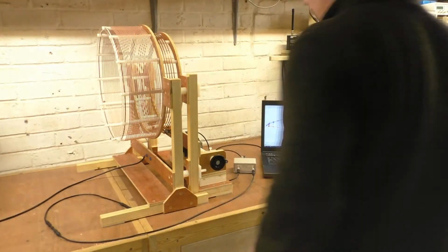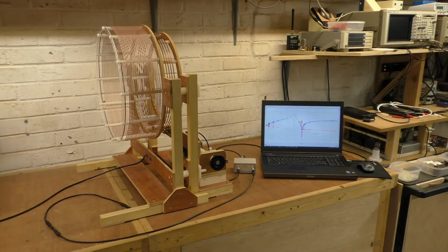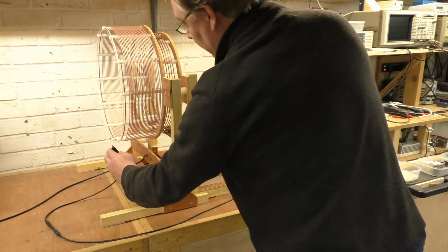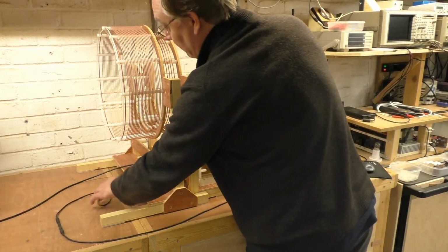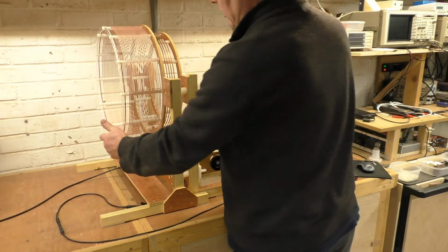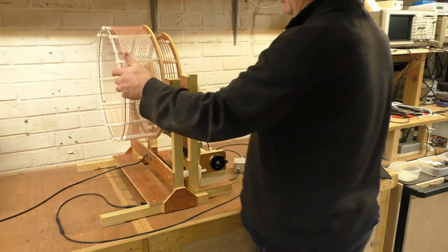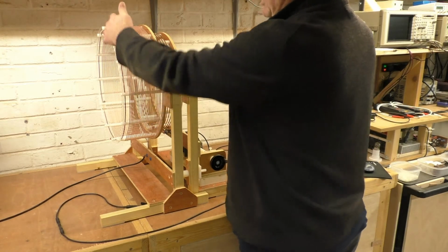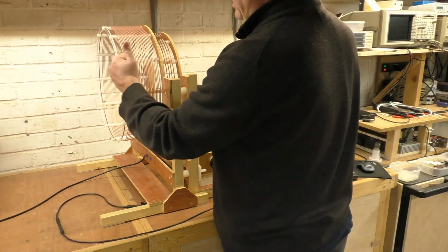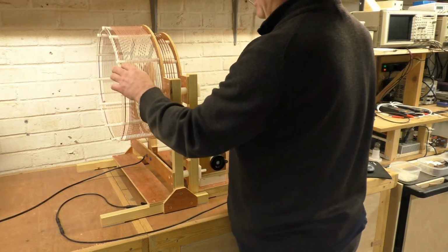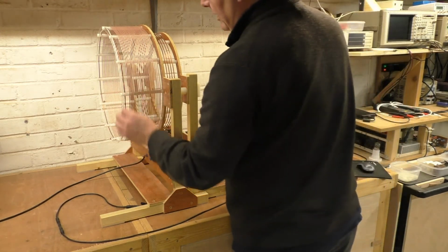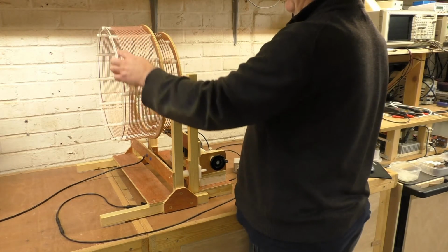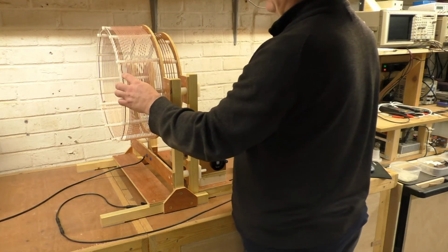So for the top end, we have this cable here, and we will look at measurements in two different ways. I have a plastic ring on the outside of this cylindrical coil. It keeps the spacing correct for the winding, but also acts as an insulated guard against the outer copper ring here. So we have a guard or shield ring as the last turn.